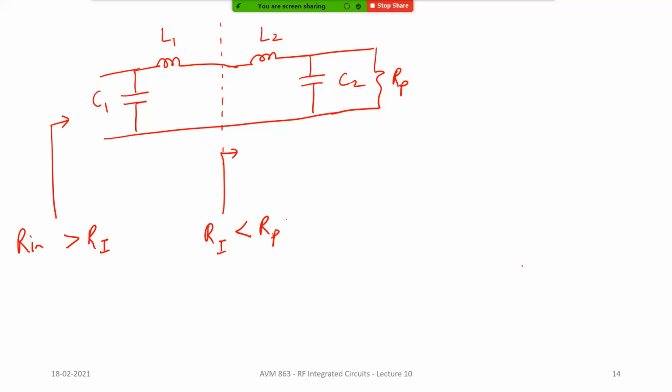You increase the area, the flicker noise reduces. But if you increase W, you increase area, and area is money in the semiconductor world. Sometimes they occupy a larger area, and the parasitic capacitances and other things will also increase, and as you pointed out, gate resistance will increase.